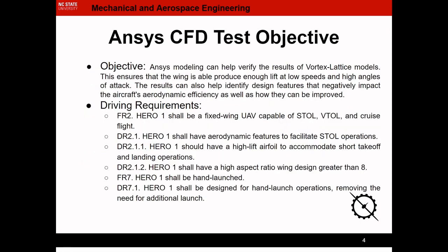So the objective of this test is to verify the results from the vortex loss models that were used for FlightStream and AVL. But more importantly, we want to ensure that our wing can produce enough lift at low speeds and high angles of attack.